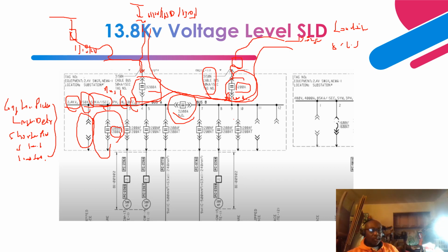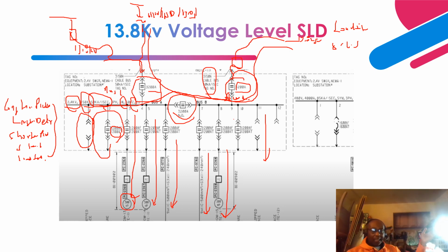So this is also another feed that goes to a motor, rated at this horsepower. This is another feed that goes to a 300 horsepower motor, and this is another feed, as you can see over here, and this is an equipped space. So this is an example of the medium voltage levels. We have 2.4 kV, we have 6.9 kV, and 13.8 kV, as a part of our ANSI standard. And that is what you see typically in North America.